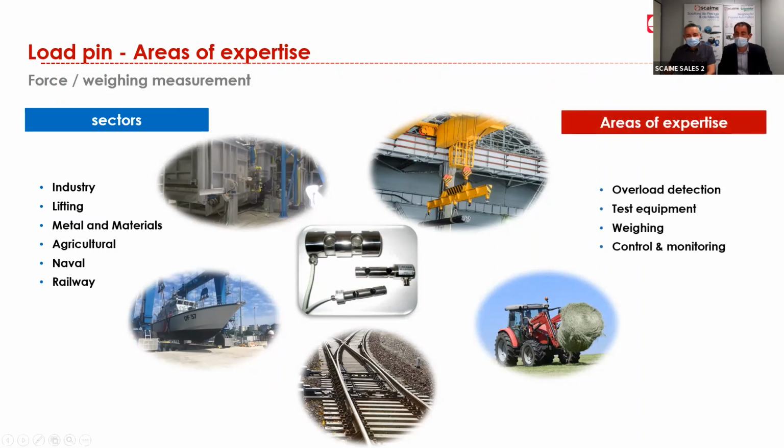The main areas of expertise for the use of load pins are overload detection, which is very common, test on equipment, weighing solutions, because load pins, even if considered a force sensor, can be used for weighing applications, but also control and monitoring applications.